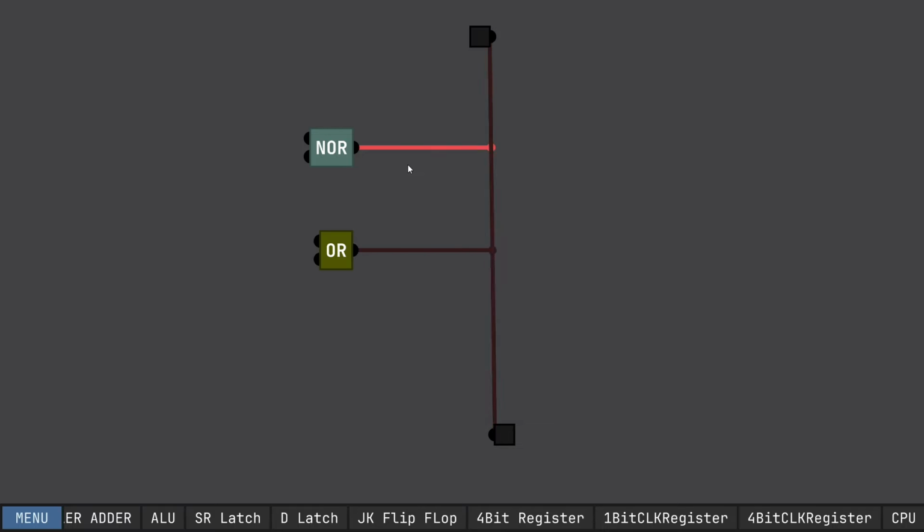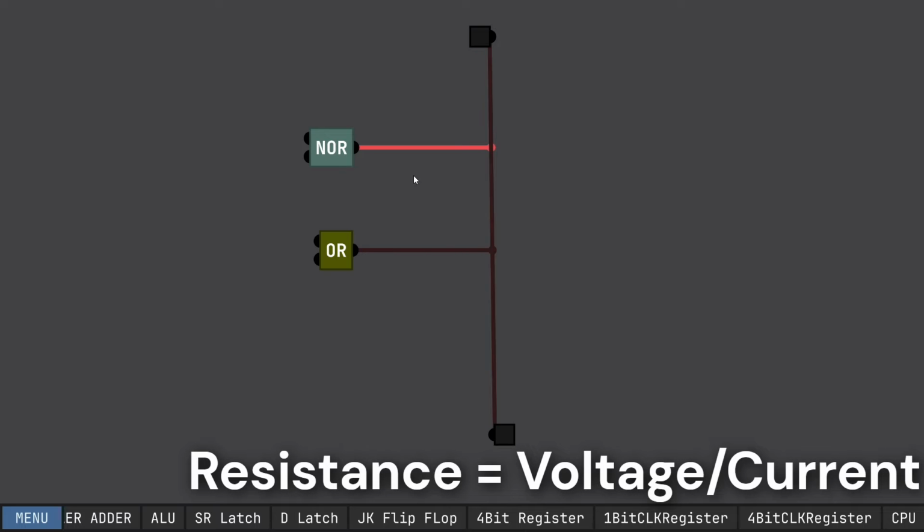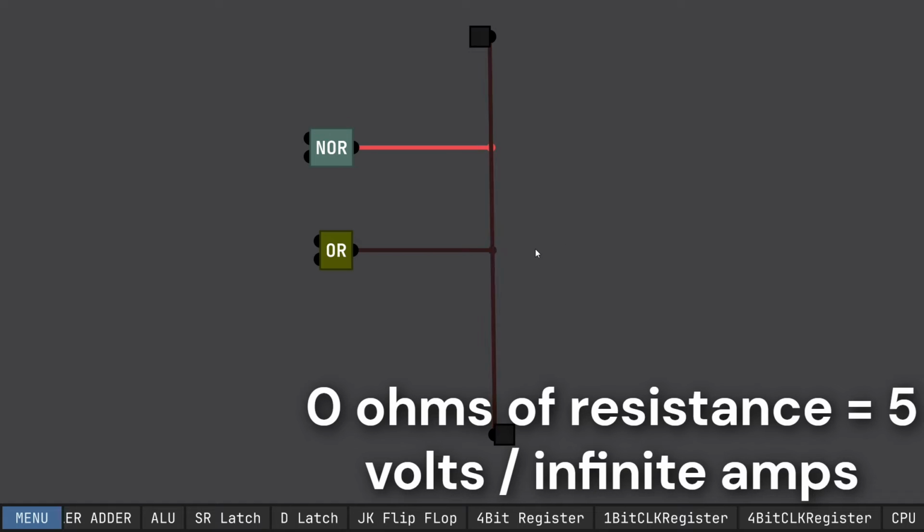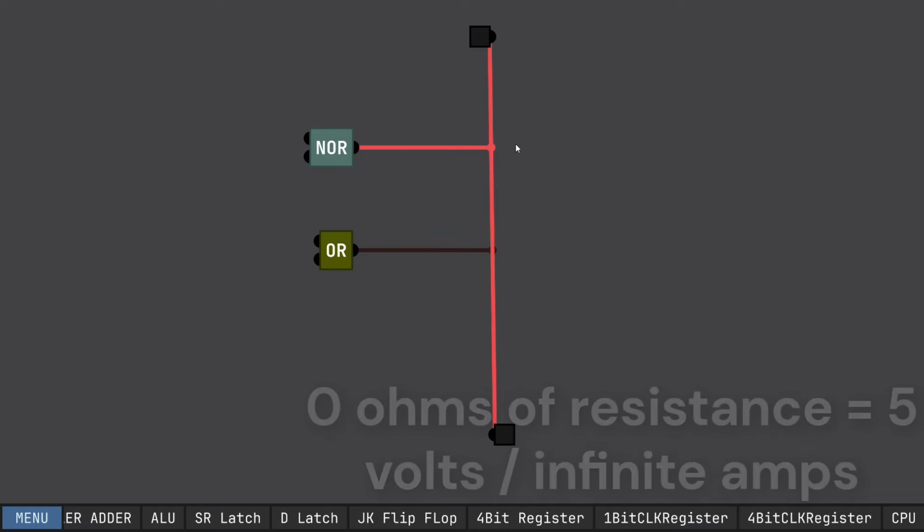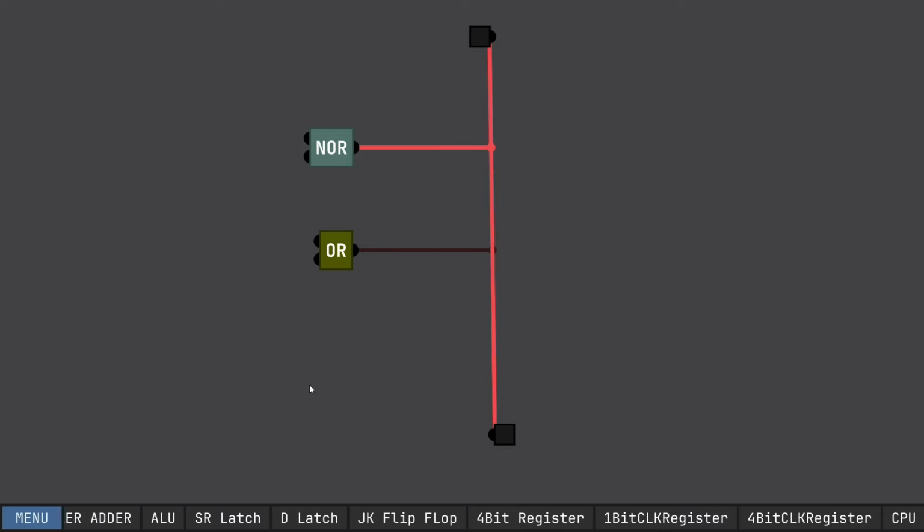But in real life, it would be a short circuit, and I'll give y'all a little electrical engineering lesson right now. If the resistance is low between a place of high voltage and a low voltage, the current spikes dramatically because of the V equals IR equation, and I'll put that on here. Because the resistance would be close to 0, and anything over 0 divided by 0 would go to infinity, that's why the current spikes up so much. But yeah, we need to fix this somehow.